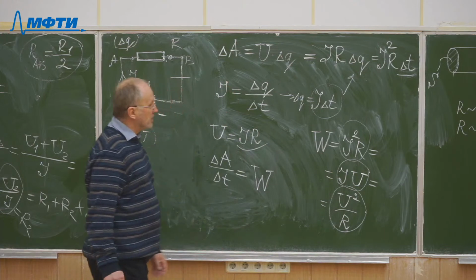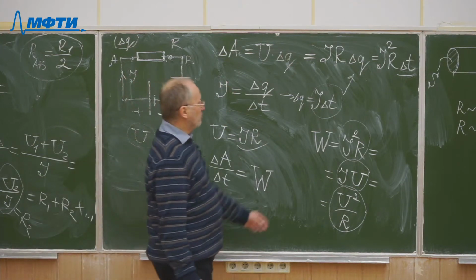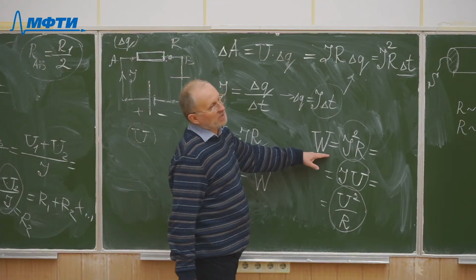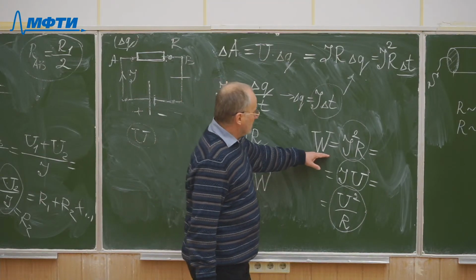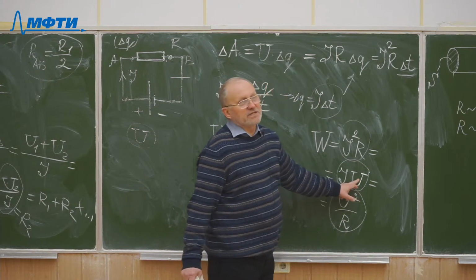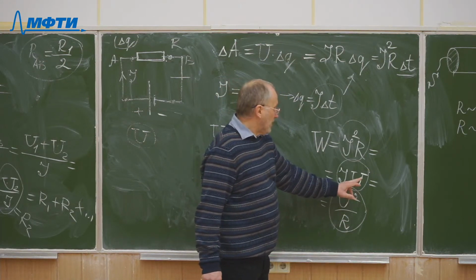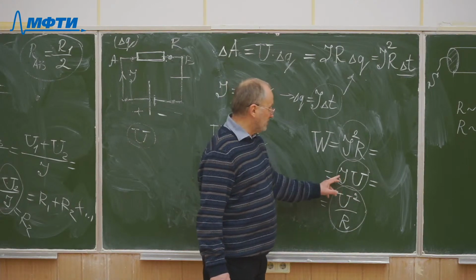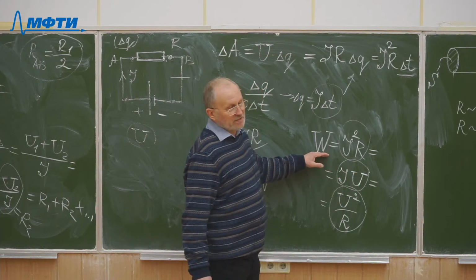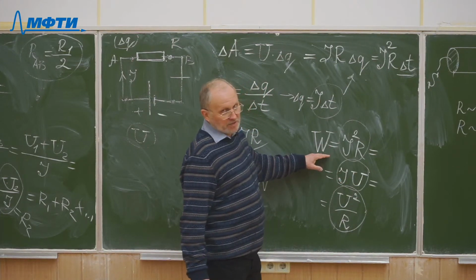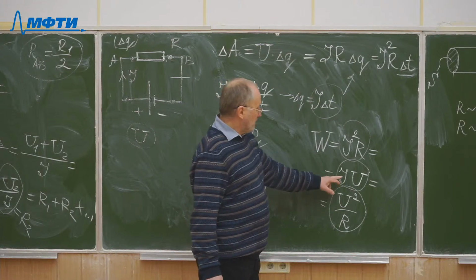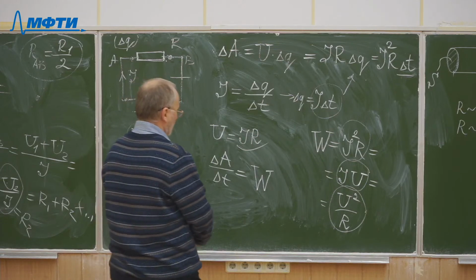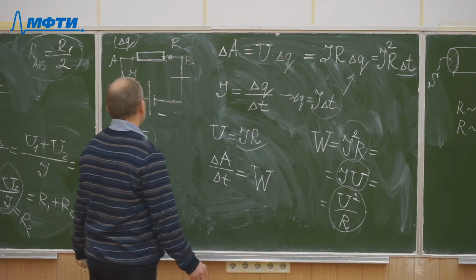You must have certain voltage and certain electric current strength in order to obtain certain wanted or desired power of electric heater. So if you want to have an electric heater of 1 kilowatt power, and the voltage is 220 volts in the circuit, then the current must be about 5 amperes, in order to obtain 1 kilowatt heating power. 5 amperes, so a fuse in your room must sustain at least 5 amperes.